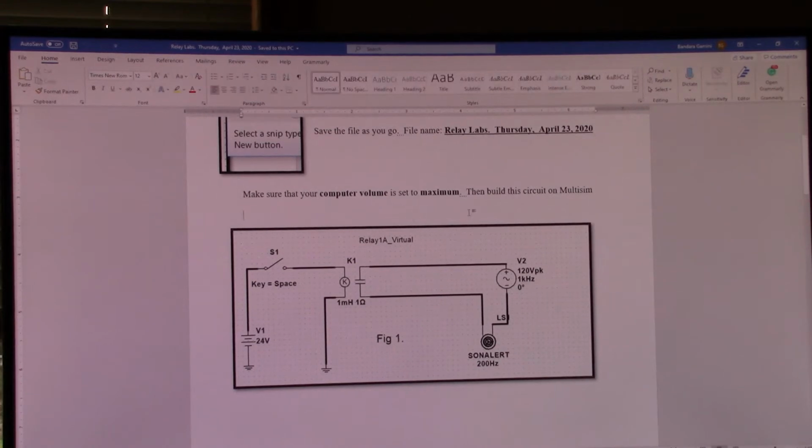So remember, the purpose of a relay like this one is you had 24 volts here as the input, and when I turn this relay on through the switch here, this coil will energize and this contact will close. If you saw the videos, which you should have, you would notice that this is a normally open contact. So when the coil is energized, this contact will close, and then I'll switch this thing on.